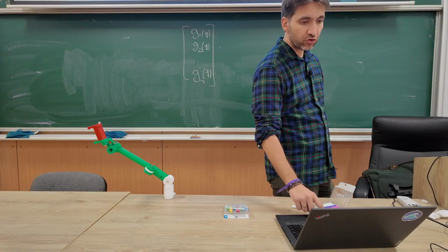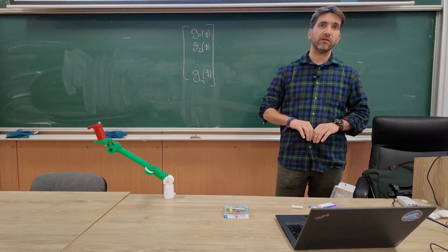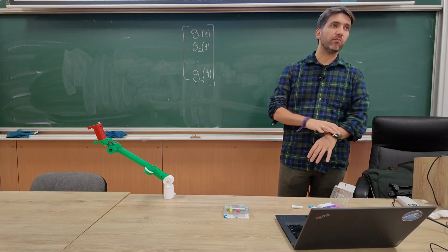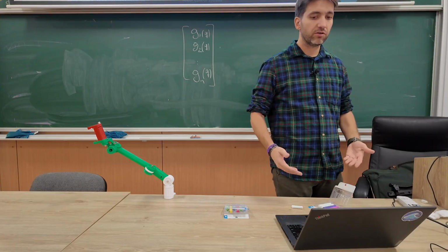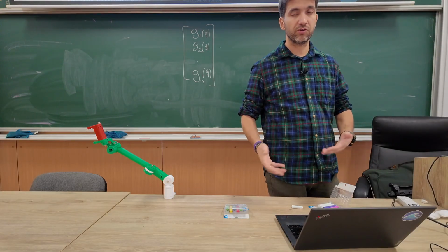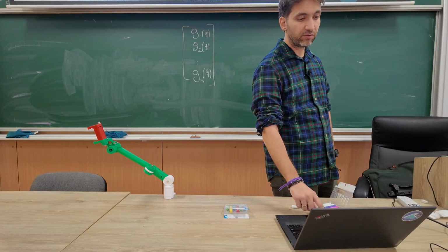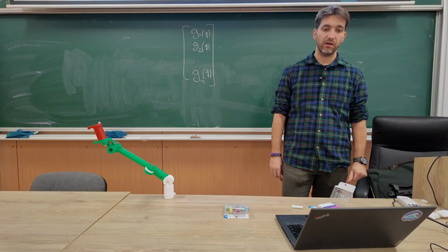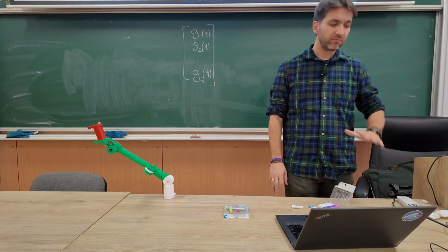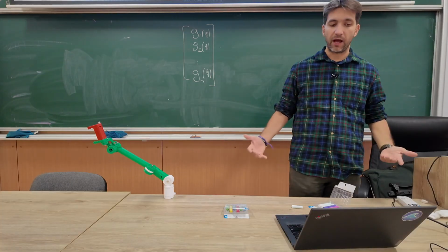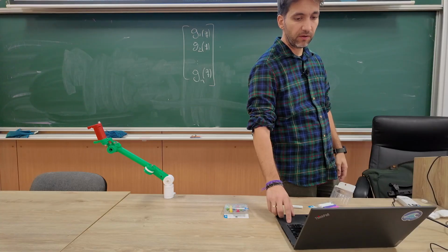If we assume that the motions are slow, then we can model the dependence of the other joints as disturbances, right? Because we always have disturbances anyway in the processes. So, to some extent, the controller should be able to deal with these disturbances, right? And then, of course, we have to tune each controller very diligently. Okay? Let's see how we could actually tune a controller for each joint.